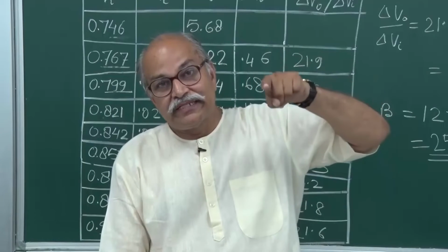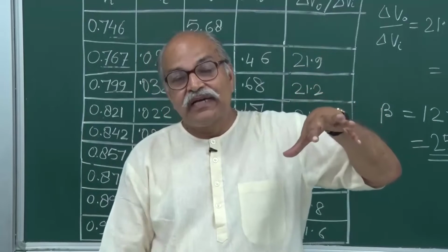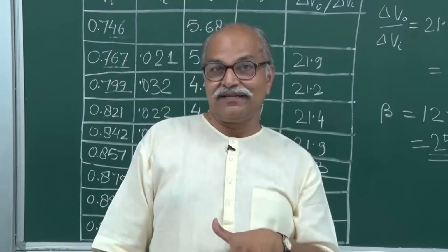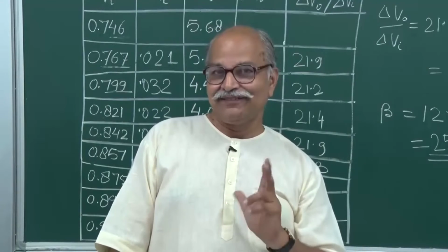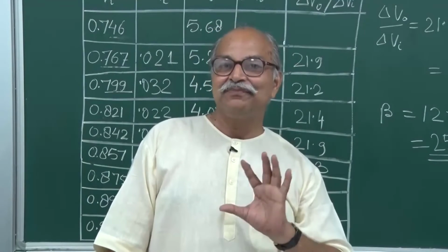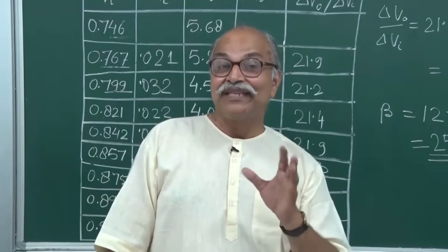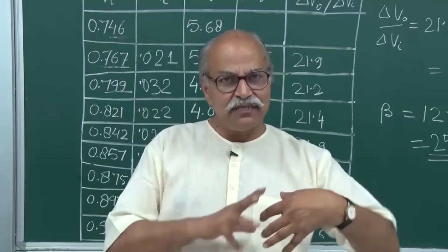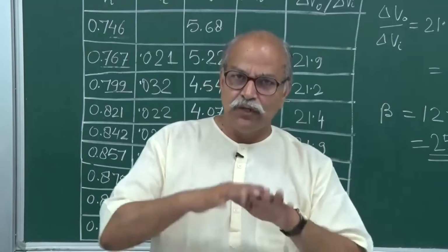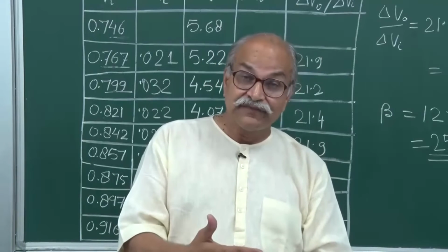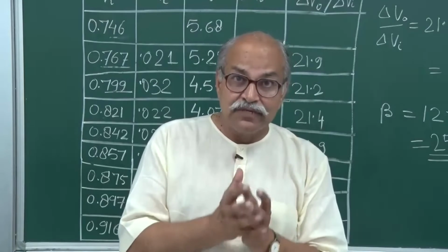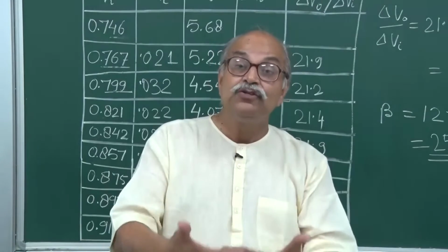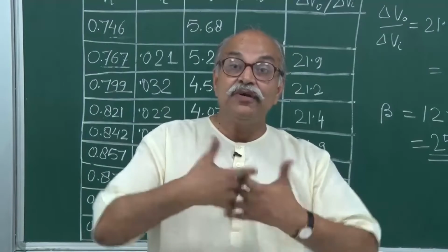So what you are doing is controlling a large current circuit through a small current circuit. You are actually doing switching in that base circuit, that VBB, that forward bias of the base-emitter junction. You are changing the voltage you apply to that base circuit from a high value to a low value, and from a low value to a high value.